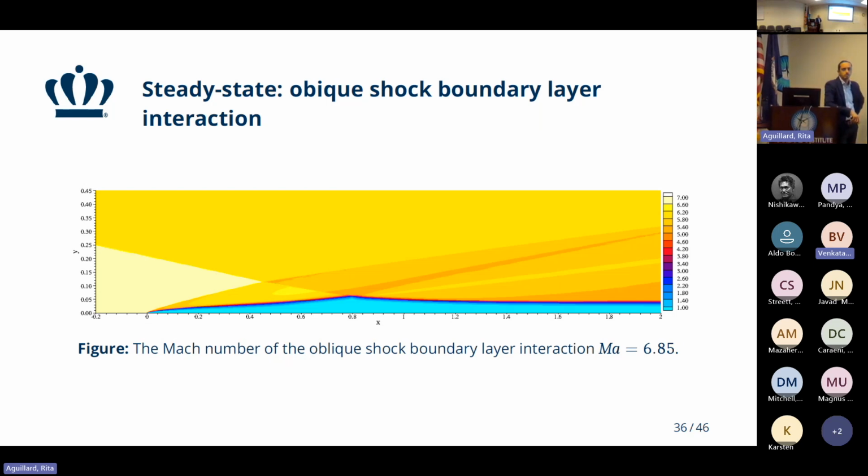One solution is that usually when we do these flat plates at supersonic conditions, we try to round off the leading edge. You could have an elliptic leading edge with a very tiny radius that would help you avoid the singularity, and that might relax the stiffness. But that is simplifying the problem, and we're trying to solve the problem as is rather than simplify the geometry.